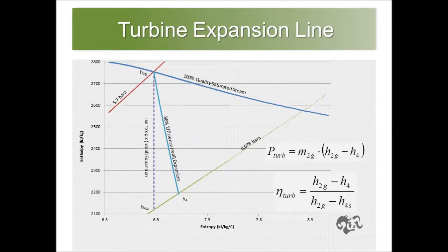If you assume an adiabatic pressure drop, one with no work or heat transfer, then you move a bit horizontally from H2G into the superheat region. This reduces your potential enthalpy drop due to the upward slope of the enthalpy at the turbine's exhaust pressure.